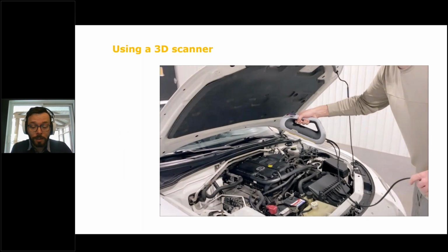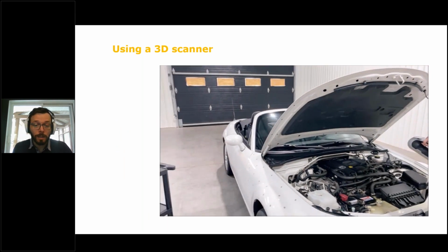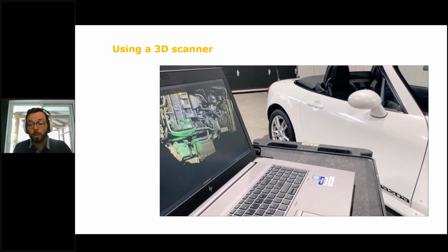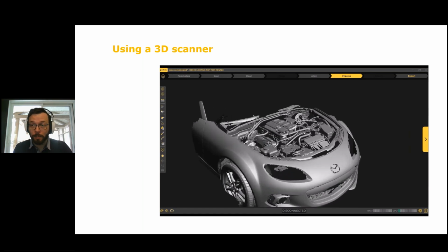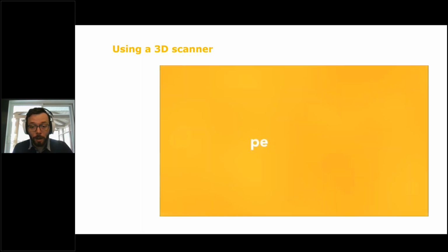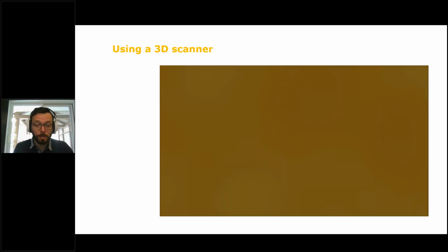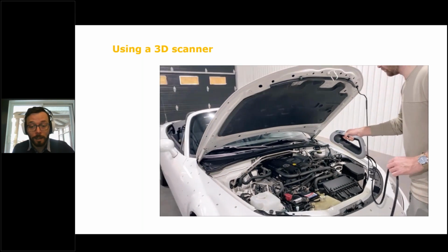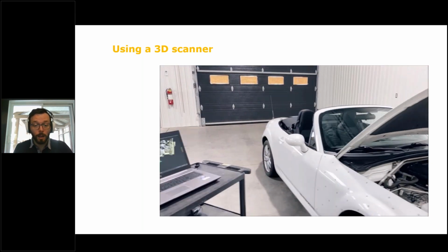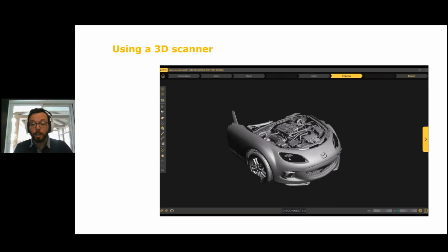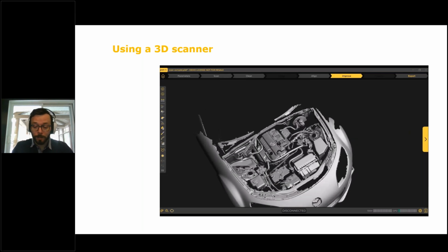This is where 3D scanners come into play. A 3D scanner is, simply put, a device that lets you bring existing objects into a virtual environment and use them as a reference. The scanner projects a line pattern onto the object. The pattern is deformed, and the deformation is observed and interpreted into 3D information. This information is collected in real time and shown on screen. In the case of reverse engineering, the ultimate goal is typically to transfer your scan to a CAD environment.